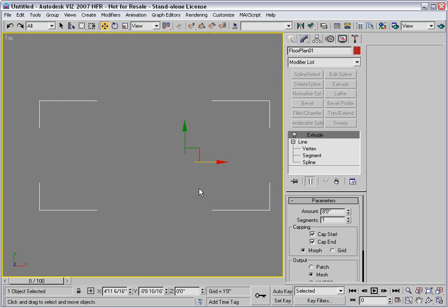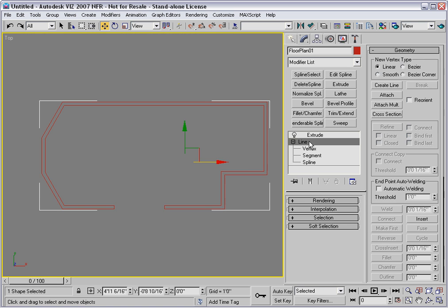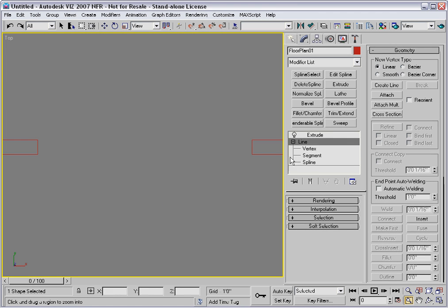Let's go back into the top viewport and go back to the line object. The problem is centered right here in the opening, so I'll zoom in there. I'll go to the vertex level. Notice that these vertices show up with the box symbol, indicating that they're the first vertices in different sub-splines. I should really only have 1 of those in the entire object, but right now I see I have 3. That tells me right away that I have duplicate vertices in these locations.